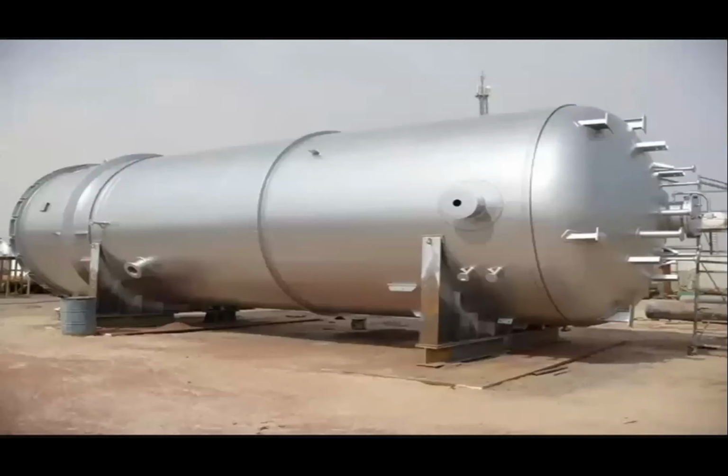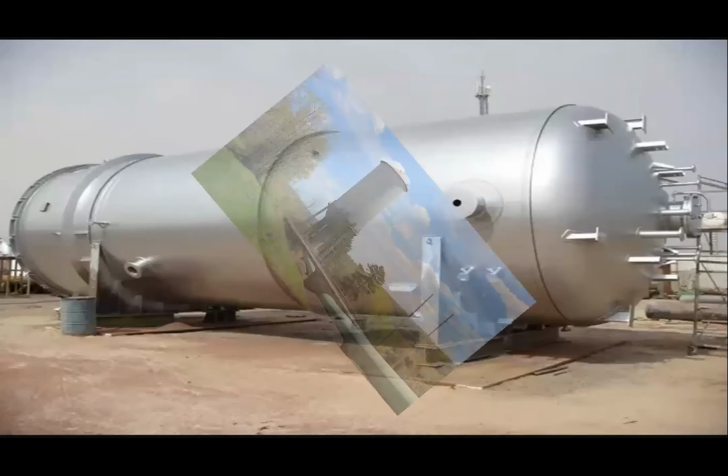There are three famous surge control devices. The first is the air vessel, and it's usually used after the pump station, to protect the system against pump power failure. And the second is surge tanks.